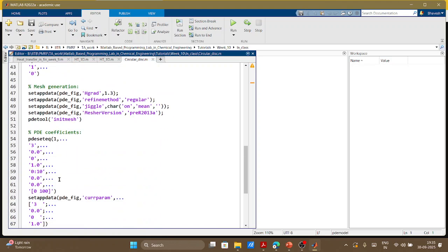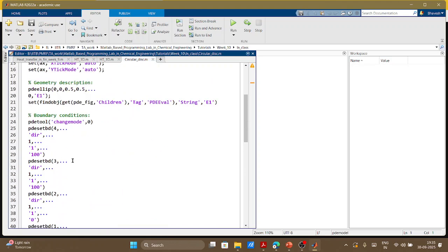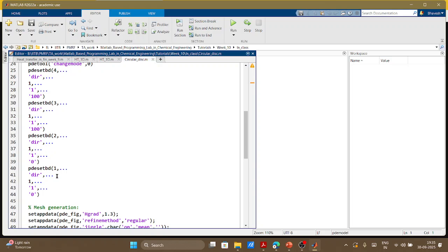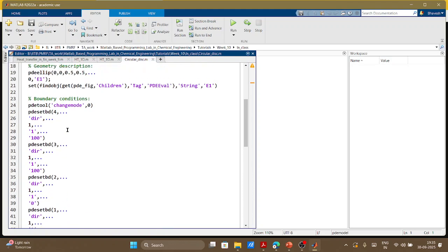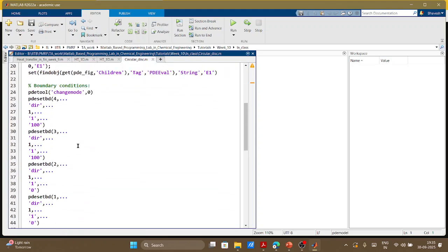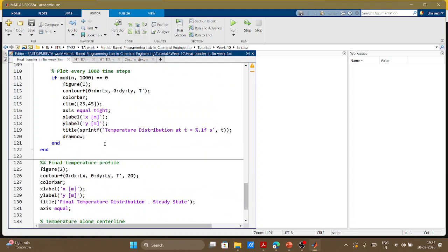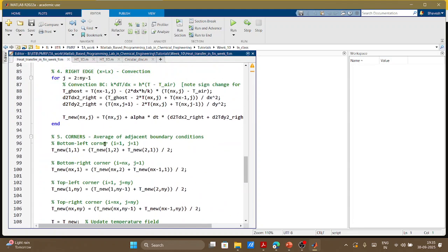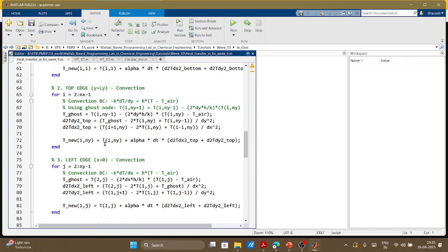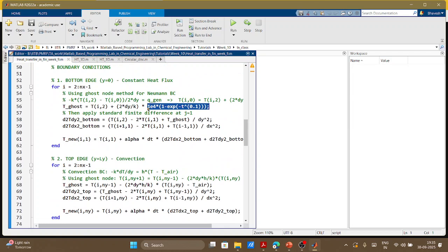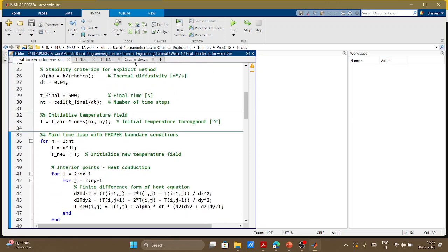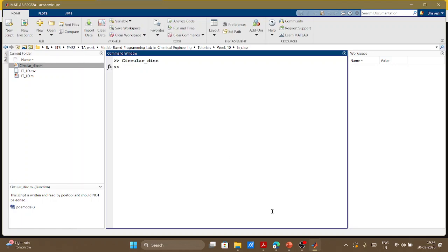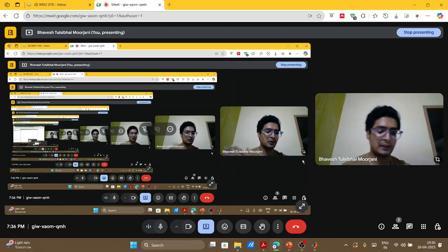So here the equation parameters are set, the boundary condition data are set, right? So the 100 and 0. Let's say if it was the gradient part, it will show some other values, right? And then you can put some variables which will change these boundary condition values. This was this previous example, right? So here you see the heat generation part is this part. It is time dependent. You compute what is the heat generation for that particular time, put it into the boundary condition and solve it. So this is how also you can use a PDE modeler to solve your time variation.